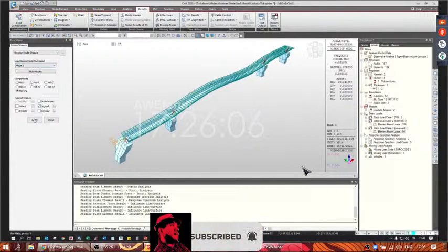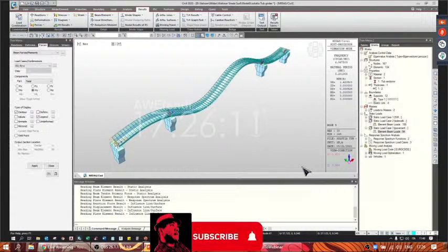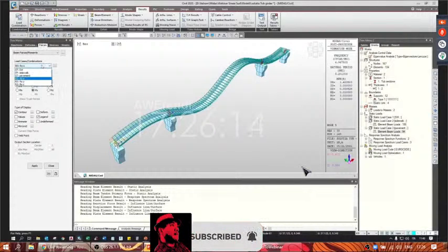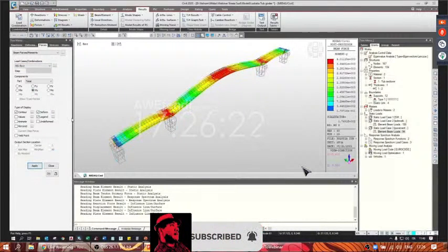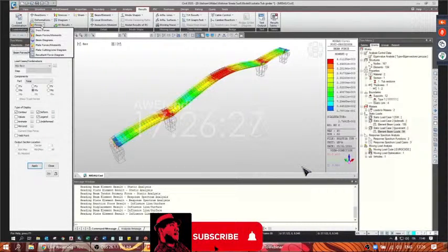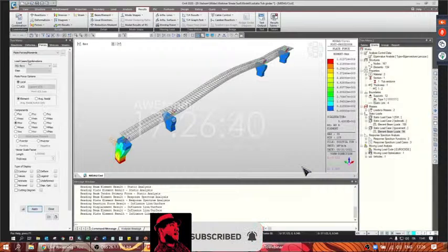Now we can give a look to the forces, the moment forces for the girder actions. We can see, for example, the effect of the vertical seism on the moment. And for example, we can see the effect on plate forces, moment between the plate elements. For example, we can see the horizontal action on the m-axis direction. Here we can see, for example, the shear force.